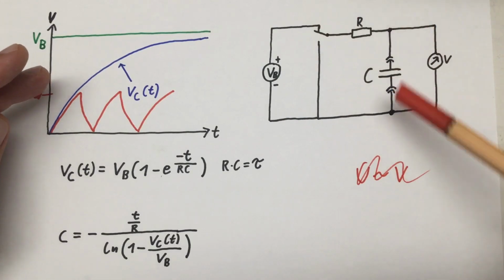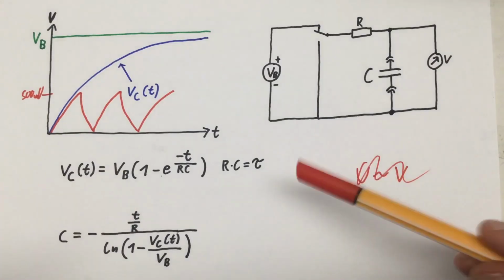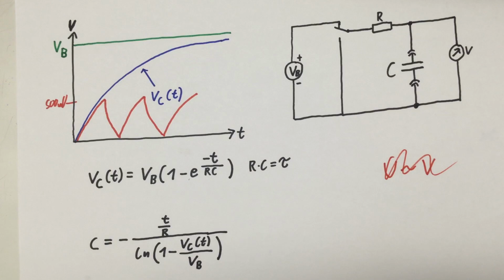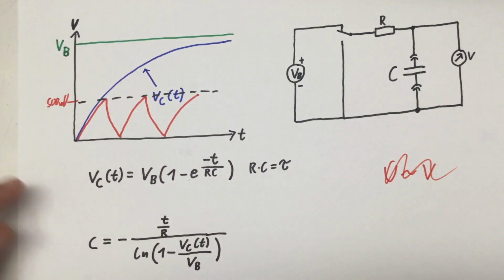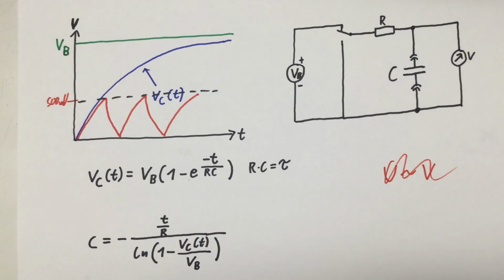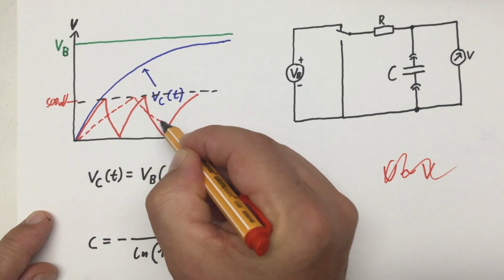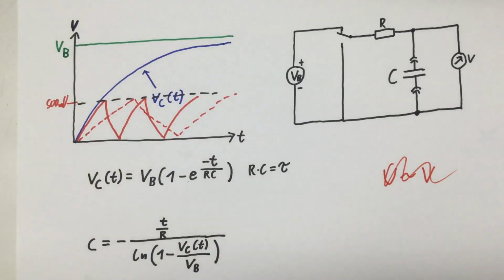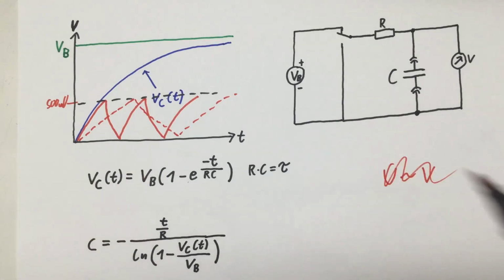The second method we had a look at last time was measuring the charge-discharge curve of an RC element, with the capacitor in the RC element, of course, being our sensor. We saw that, for example, my Brymen multimeter does that by charging and discharging the capacitor to a fixed voltage level. I think it was 500 millivolts, at least that's what I've written here. And we also saw if the capacity is increased, of course, the frequency of this charge-discharge cycle decreased. And that brings us directly to our third method. Just use that RC element in some kind of an oscillator and just have a look at the frequency of that oscillator.